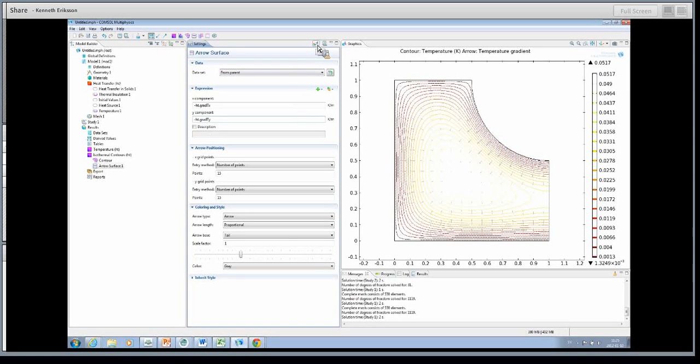So heat is now flowing out from the hottest area here in the direction of the boundary where we have a zero boundary condition. So heat is leaking out of all parts of the boundary except this one to the right, where the temperature stays constant across the boundary because of the isolation.